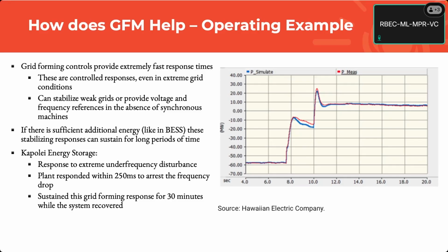So the takeaway, if you're not here till the end of the day tomorrow, is that grid forming controls inherently are more stable because they're not doing anything in that fast control response time. The same as a synchronous machine. So there's nothing inherently preventing you from making everything grid forming. We have a lot of caveats around that, and Alex gave some of them.